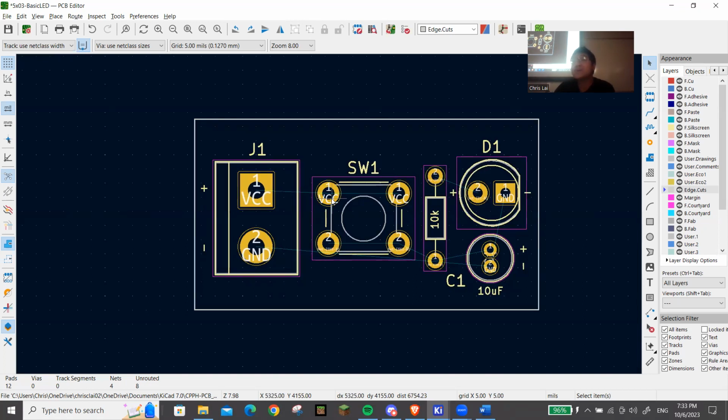All right, just to recap, this was step 3 of PCB design, right? Step 1 was circuit schematic. Step 2 was assigning footprints. Step 3 was placement and labeling. Step 4 is routing. This is the fun part because then you get to get rid of all those nasty blue rat's nests by connecting wires to all the components.